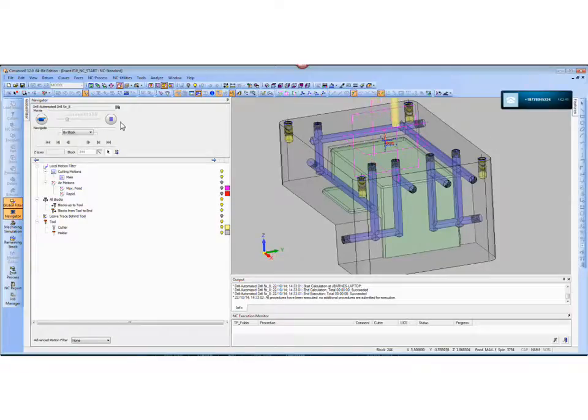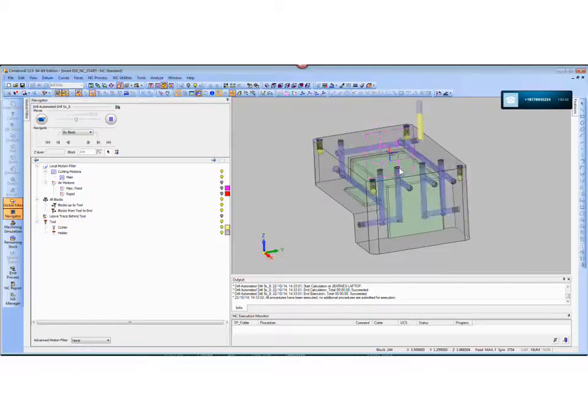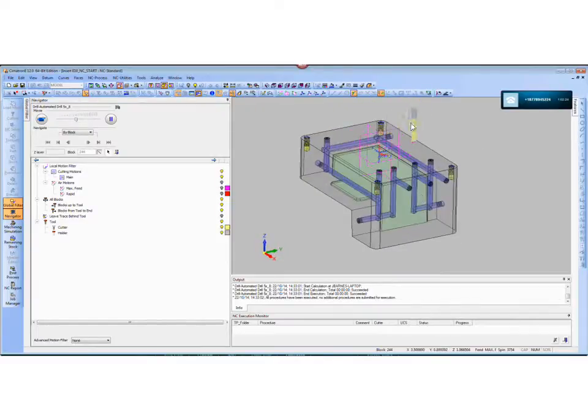Okay, so this drill is going to go in, and it's going to either drill the hole completely, or it's going to at least give me a pilot depth for a longer drill. And you probably noticed that the software is optimizing the order of the drills. When it had the center drill and the spindle, it went in and center drilled everything. And now that it has the 438 tool with a 5 times length ratio, it's using that drill everywhere that it needs to be used and not wearing out the tool changer going through all the processes.